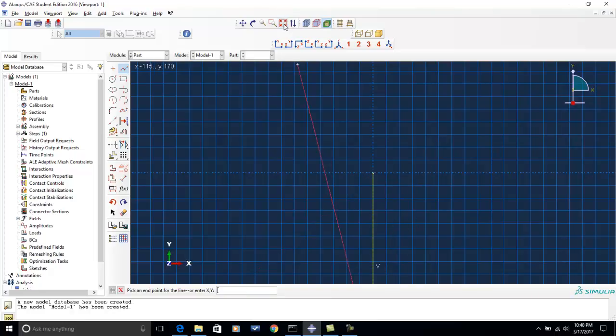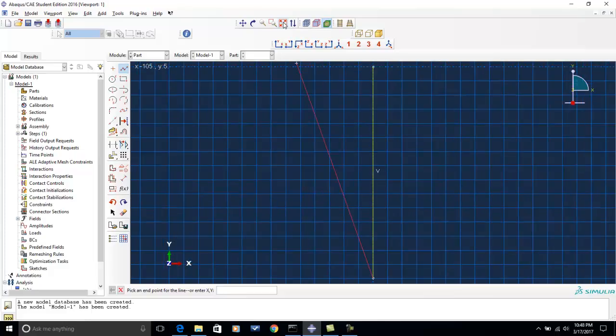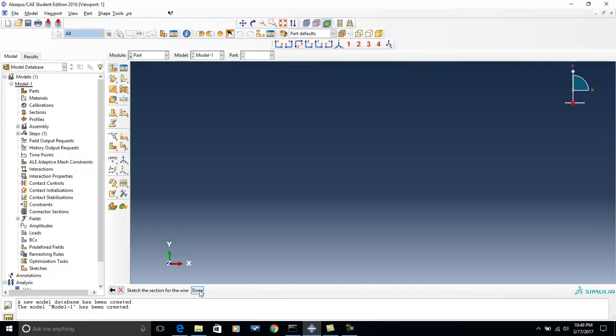If we want to be able to zoom so we can see the whole thing, we can click on this button up here at the top, the Auto Fit View button, and now we can see we just have a straight line. We're done drawing that line, so we'll click on the little X here to exit out of that tool. And this is the only line we needed to draw for this part. So we'll now say that we are done. And there's our first part, part AB.